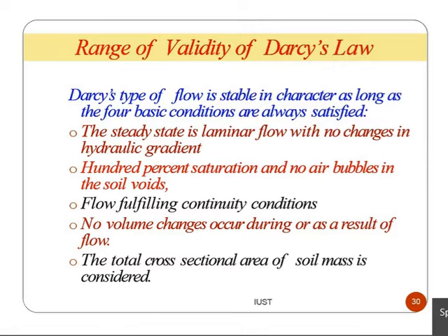100% saturation and no air bubbles in soil voids. That condition may be possible, because if we drain some of the water and after that measure the hydraulic head differences and the flow rate, that condition is preferable. Flow fulfilling continuity conditions, like no leakage or discharge being removed from the system. No volume changes occur during or as a result of flow.